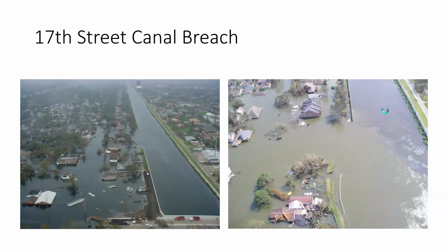There you go. So this is one of the cases. I thought it's an interesting case study, which is the 17th Street Canal breach. If you can see on the right side of the picture, this is a levee with an I-wall on it. The failure pushed the levee 40 feet laterally, and when the flood dried out, they found that the levee was inclined 45 degrees.